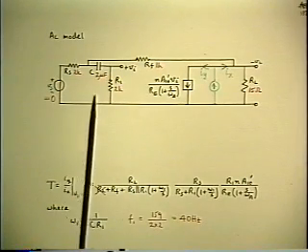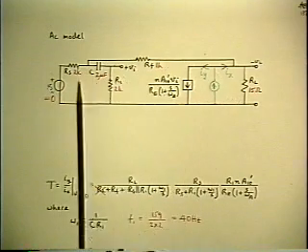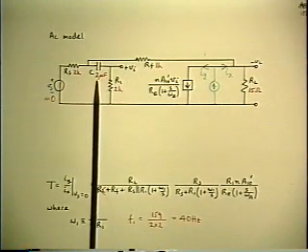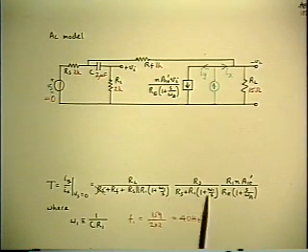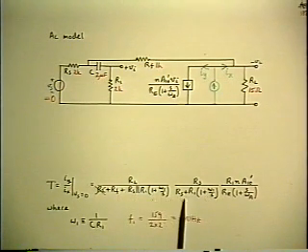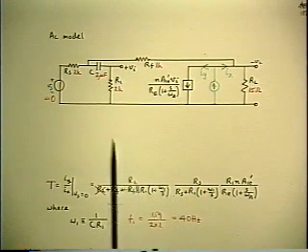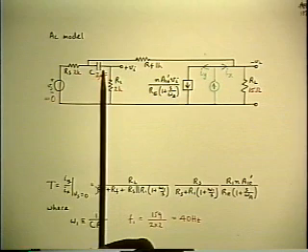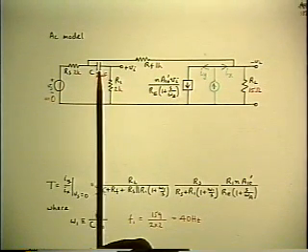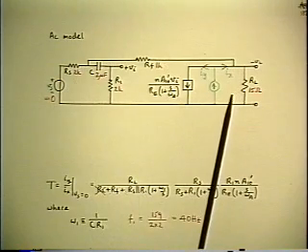That's exactly what we have here. The calculation we've done involves only one reactance. So rather than doing the algebra to put this into factored pole zero form, let's simply drop the C to begin with by replacing it with a short. Obviously we choose a short this time and not an open, because if you take an open you're going to get 0 for the loop gain.